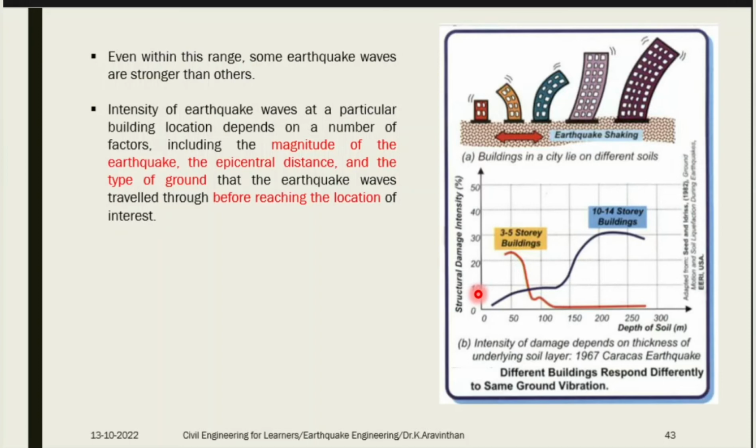They will take these three sets of data and understand, for example, that if 100 buildings collapsed, only tall structures with more than 10 or 15 floors are getting collapsed. They have taken the statistics from a particular earthquake and given this data. Earthquakes also depend on the soil, which I discussed in the last class. If the soil is very weak and poor, your building will vibrate with much higher amplitude. If your building is located on strong soil, it will not vibrate to a higher amplitude. Only slight shaking will be there.